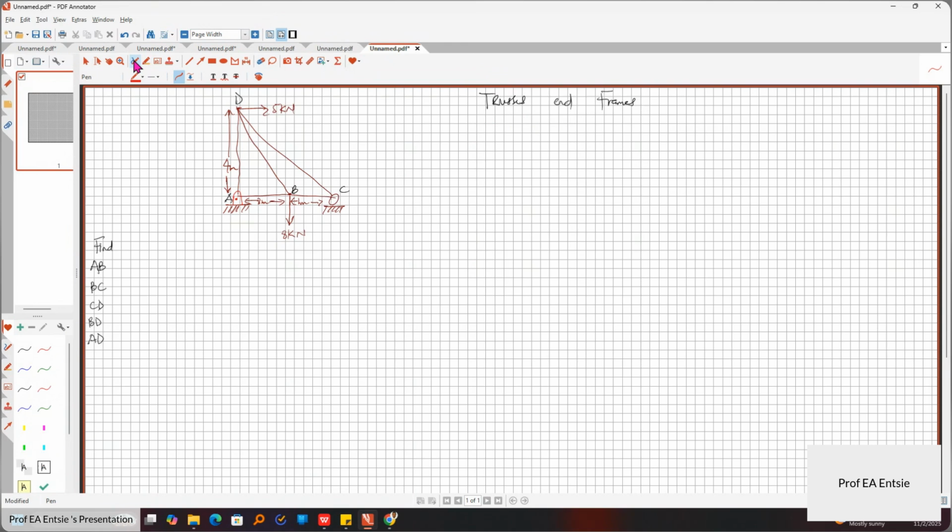It depends on the method that the company wants to use to finish the work. If the company wants to develop a truss system in a shorter period of time, then they can do the analysis with the method of sections. If they want to take more time, then they will use the method of joints, and you should get the same answers, the same forces, the same members, everything should be right.